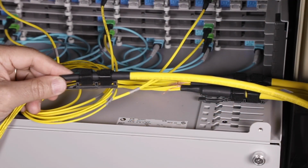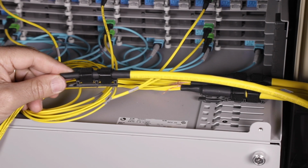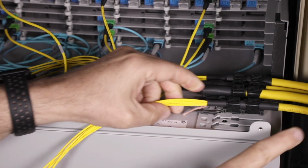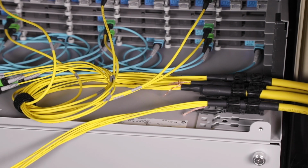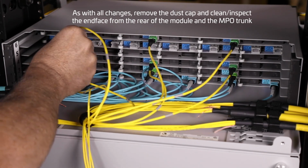Since SN modules are twice the density of LC modules, we need to install another trunk cable in the rear of the panel. You can either install the new cable and clip into an empty slot, or you can add a new trunk to an existing bundle by simply removing the hook and loop, adding the trunk, and resecuring with hook and loop. Insert the MPO connectors into the rear of the modules.